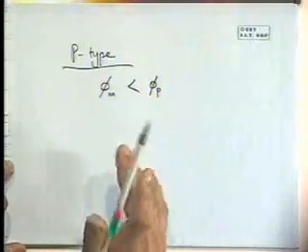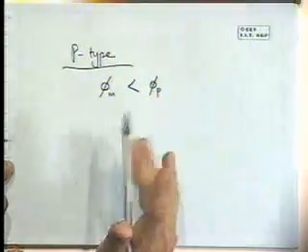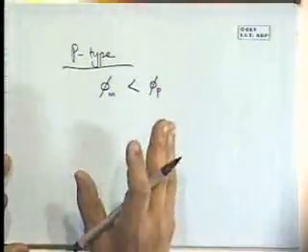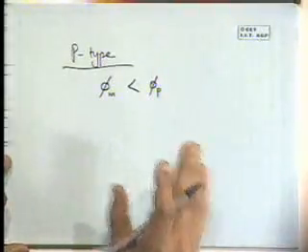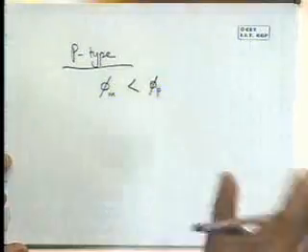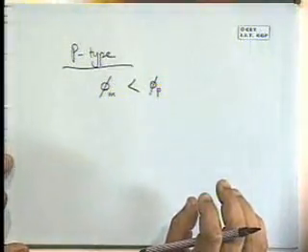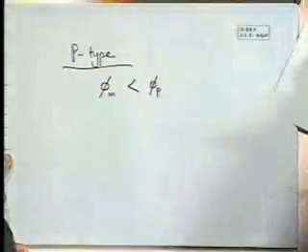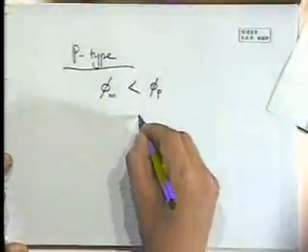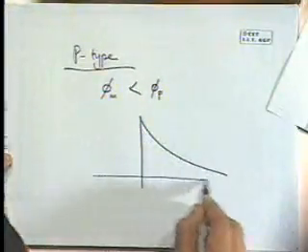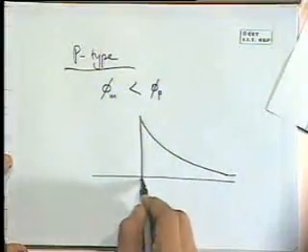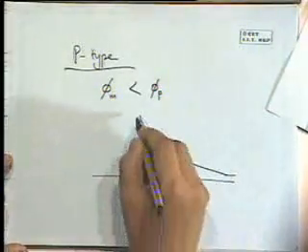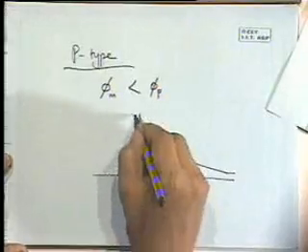Now, this theory, which is thermionic emission theory, is a very simplified version of what actually occurs. In many semiconductors, if we look, we will see a completely different behavior. And I don't have time to go into all of it, but I'll point out a couple of things quickly. We have this situation roughly where the metal semiconductor, the barrier is there, and this one is phi B.